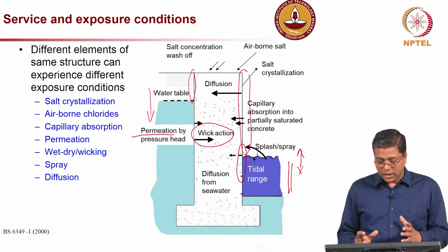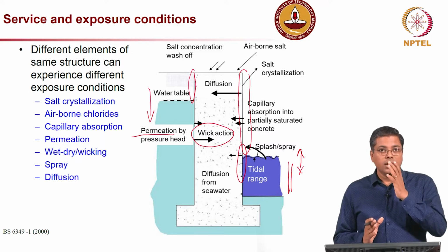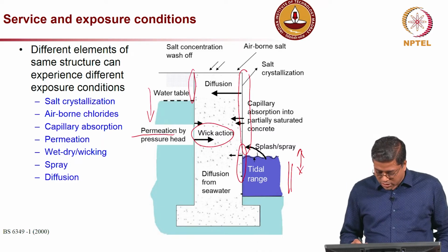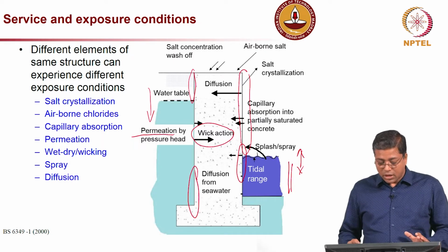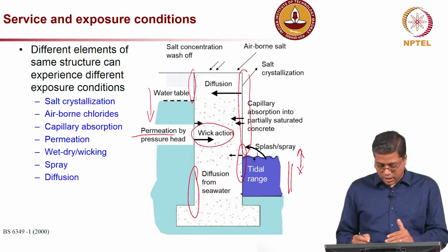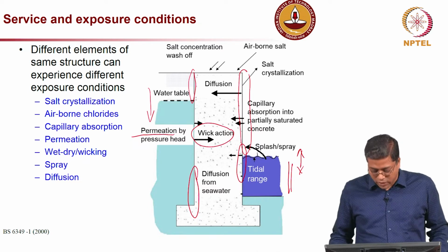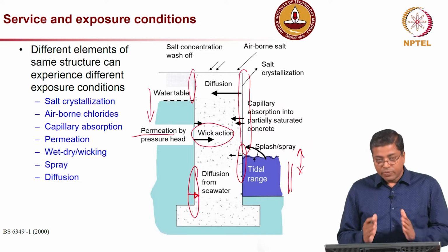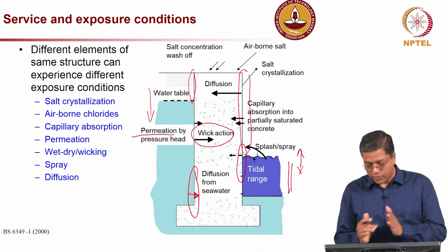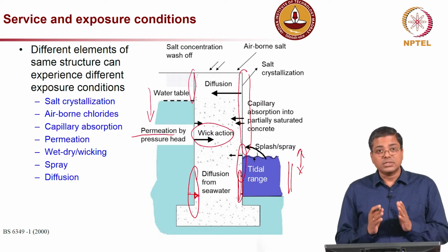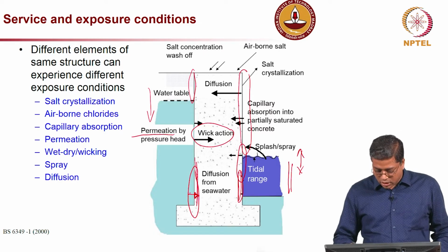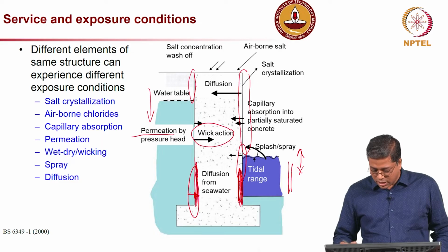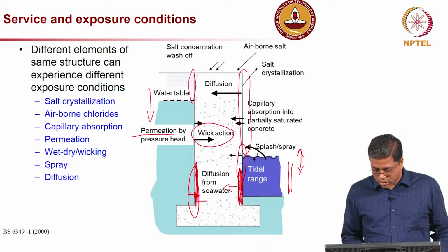Before going there, I would also like to mention that at the bottom, if the exposure condition is really wet, you can also have diffusion, because once the water or the chloride solution gets into the concrete and gets deposited at the near surface of the concrete, that chloride can diffuse into the concrete.